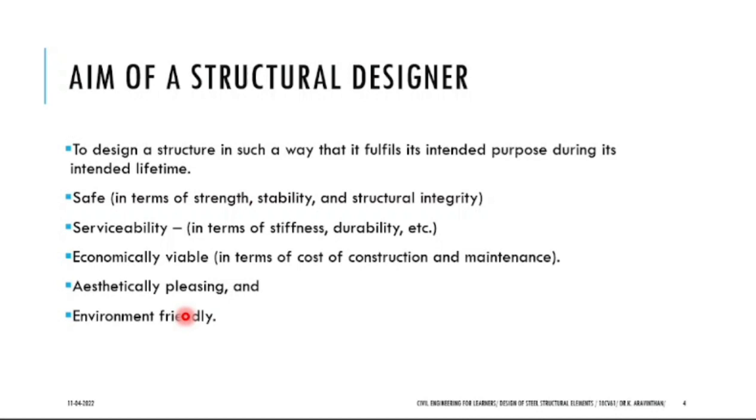When constructing, a structural designer should also consider that even though you might get 1 rupee less, you are not allowing the environment to get disturbed. So you can prefer to spend that 1 rupee and reduce the environmental issues. For example, if you are constructing a structure in Delhi, Delhi is a place with a high amount of air pollution, yes or no? Frequently they have air pollution. So in those areas you can prefer fly ash bricks. Where you have less air pollution, in those places you can go for red bricks.